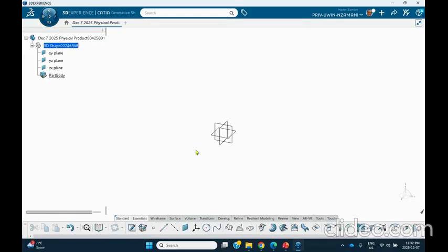All right. Next thing I will do, this is going to be my file, but I'm going to import those two step files. Now, when I import it, it doesn't go into this file directly. It opens up by itself. I'm going to copy and paste the stuff that I want from it. So let's go ahead to here, this one, import.